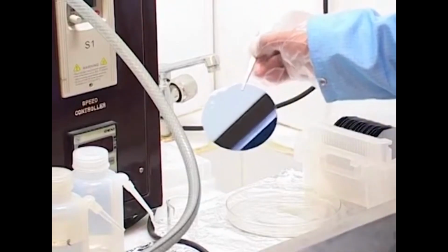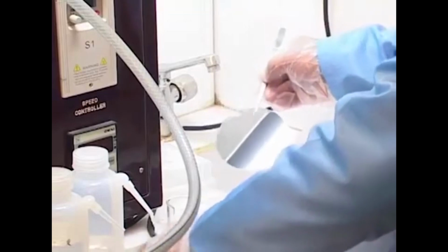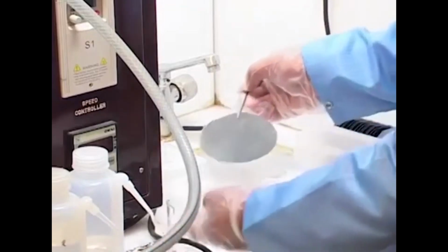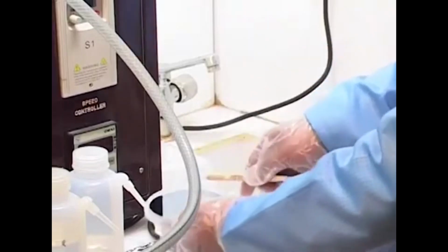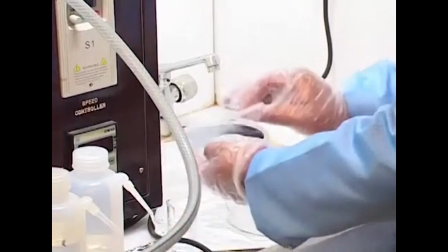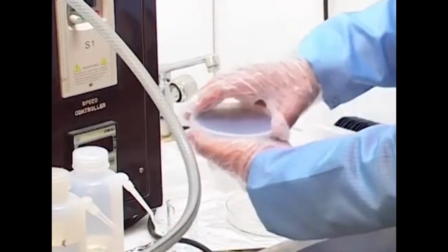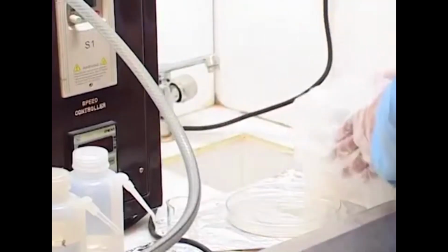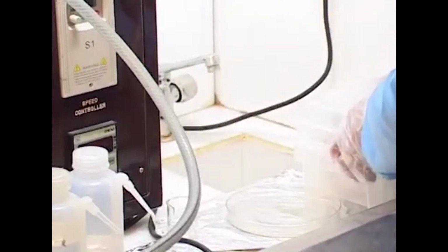Tweezer also is a very clean tweezer, and then essentially we use this box to load this wafer, and later on all the handling will be done using this particular box in the subsequent process steps, and then cover this with the lid. Okay? We close the silicon wafer box and keep it in a separate area.